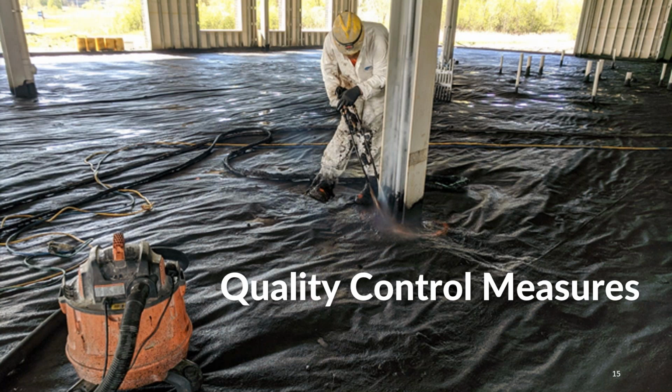They are going to conduct thickness verification of the spray applied layer. They're going to perform smoke testing to seal up any pinhole leaks or areas that need to be sealed up that you wouldn't be able to identify from just a typical visual inspection. And then we often recommend a third-party inspector to be out on site to document and oversee the installation and the QA/QC that's happening out on site. That could also include a pre-pour inspection of the membrane to identify any damage or repairs needed prior to concrete placement.